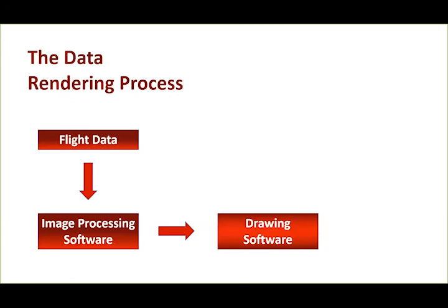And then ultimately you can bring them in as an image into most of these forensic CAD programs, and most of them have the capabilities that if two points of real world, maybe two measured with a steel tape, maybe like from a manhole cover to a storm drain, something that is visible in your diagram, then these programs will allow you to scale those images based upon those 2 points, and again, to better give you a more accurate, if you're drafting, lines, maybe pulling measurements or placing vehicles.